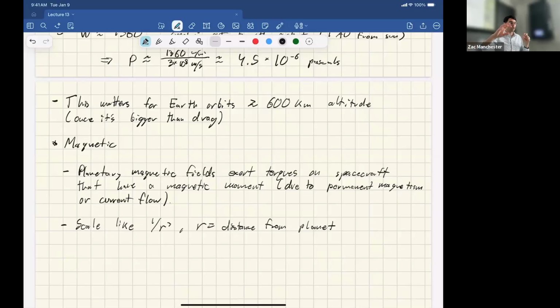So if you care about really good magnetic field measurements, you don't have to get very far away from the spacecraft bus before this tails off quite a lot, and you get relatively clean measurements from the magnetometer. So a standard move to get clean magnetic field measurements on spacecraft is to stick the magnetometer out on a boom a few meters from the bus. It turns out you don't have to go that far for this r³ to really help you with the kind of noise from the bus getting knocked down several orders of magnitude.